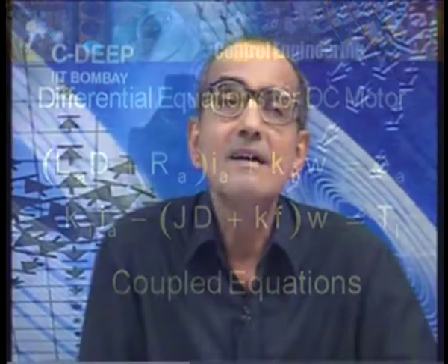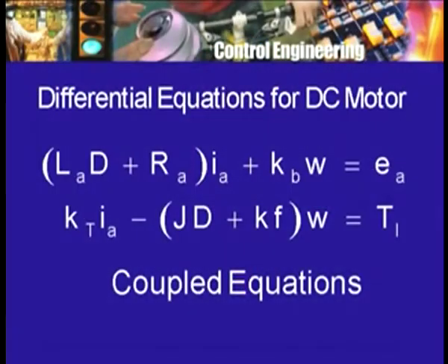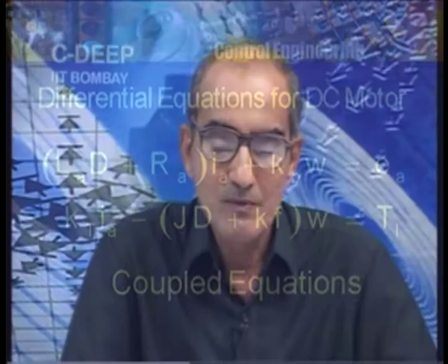Now, what we did earlier was to apply the Laplace transformation to these equations, whereby the D was replaced by S on the left hand side. Of course, because of the derivative property of the Laplace transformation involving initial values, we did obtain initial conditions or initial values of omega and IA. Those terms we transferred to the right hand side and said that we will not look at them, or will assume that the initial values are 0 equivalently.